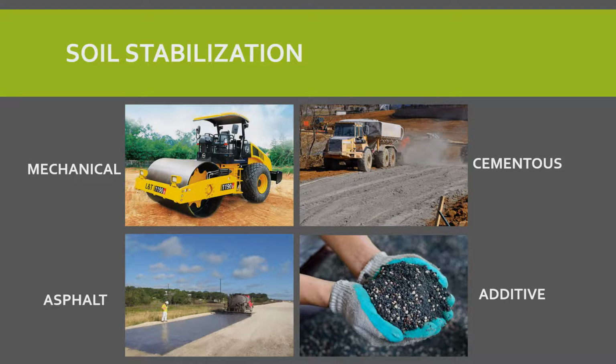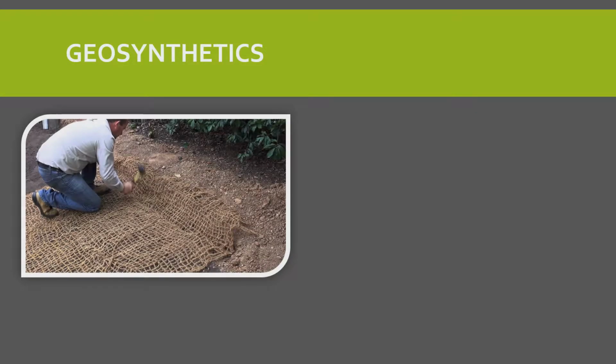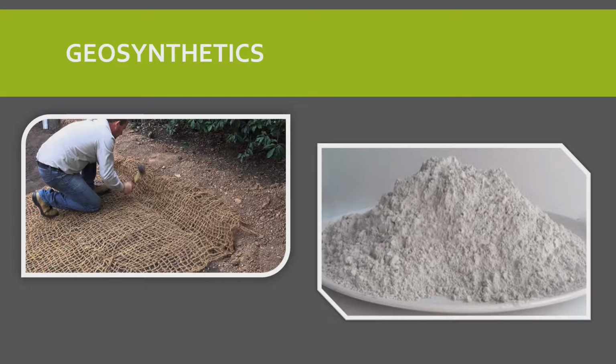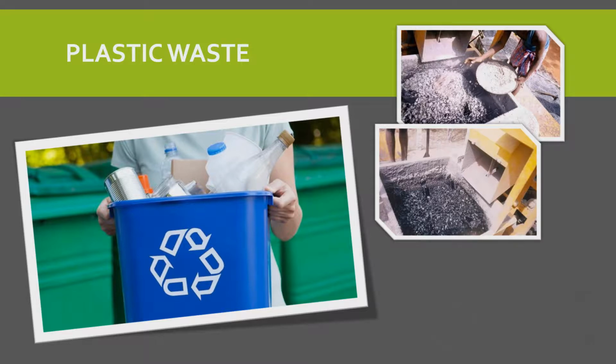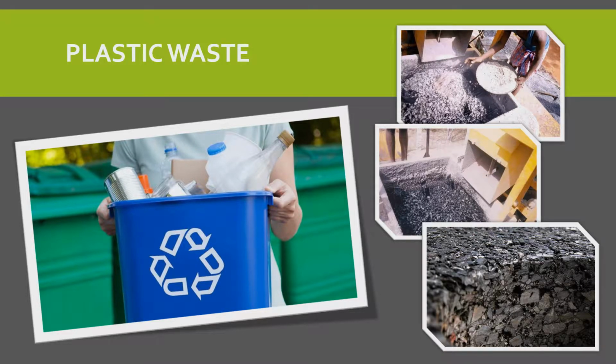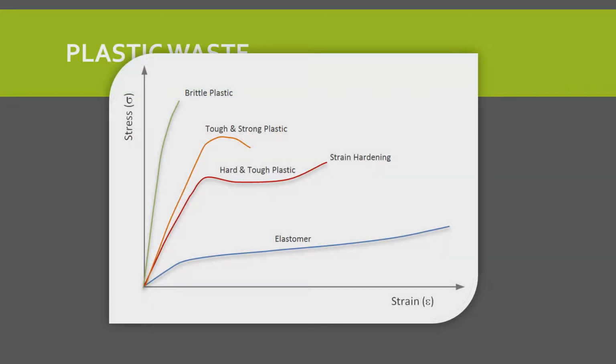Several geosynthetics include the addition of coconut fiber with tensile property, which generally helps soil to prevent shear failure. In addition, cementitious-like product waste such as furnace slag and fly ash were also used to stabilize weak soil and to assuage its deteriorative effect on the environment. To address the Philippines' problem concerning both plastic waste and weak subgrade, plastic waste were added to the subgrade to improve its condition. At certain composition and minimal material processing, it can improve both strength and physical properties of soil.